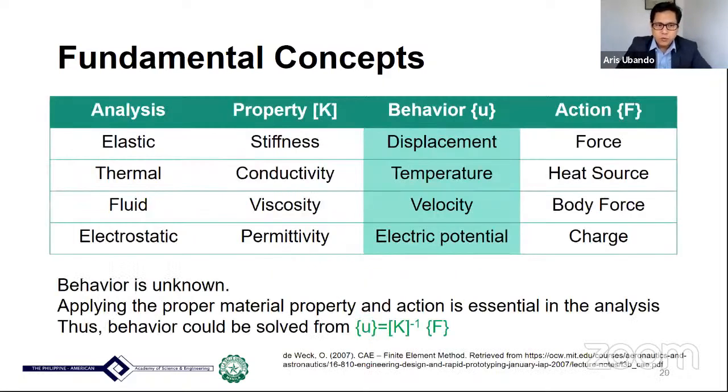What we want to do is isolate U, solve for U. We have different types of analysis for elastic, thermal, fluid, and electrostatic, wherein we have sets of K: stiffness for elastic analysis, conductivity for thermal, viscosity for fluid, and permittivity for electrostatic.